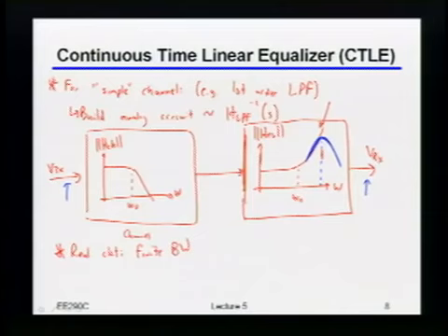Should be half the bitrate. Yeah, okay, so somewhere between half to about 2/3 of the bit rate is where you typically put it. But basically, it's directly related to the bit rate. And it's usually on the order of, as you said, half to maybe 2/3 of the bit rate. If you're interested in where that number exactly comes from, you should come talk. But ballpark, that's where it is usually.